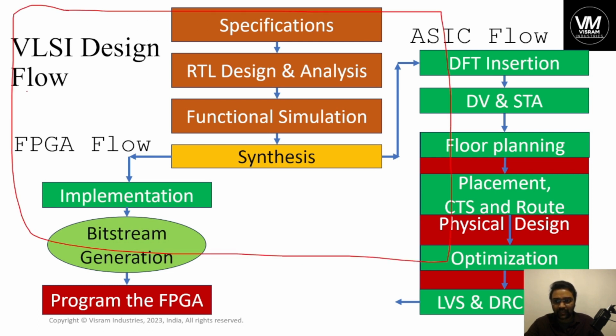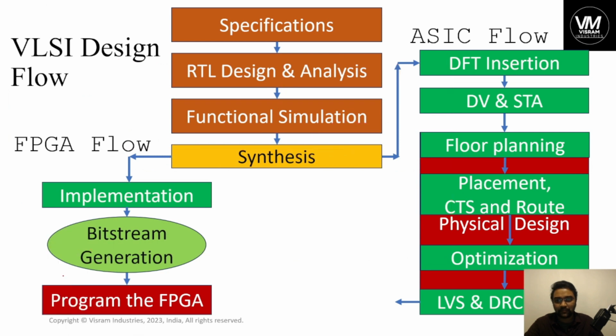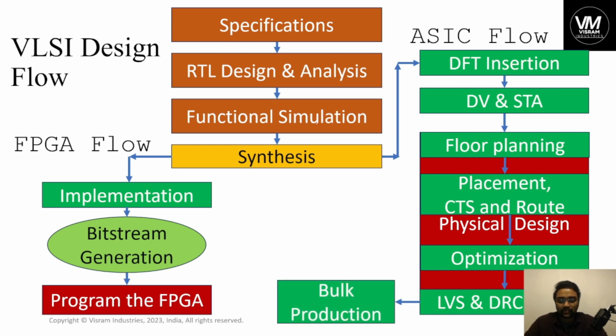In this window, you can see some timing charts, and you can see some hexadecimal codes written in this form. So this type of simulation window is provided by using the graphical user interface. Some EDA tools have that. Most of the EDA tools will have that. You have to invoke the graphical user interface. One command in TCL scripting, start_gui, gives the GUI window. So after we make the design possible in the ASIC design flow through all these steps, you can make this chip ready for bulk production.